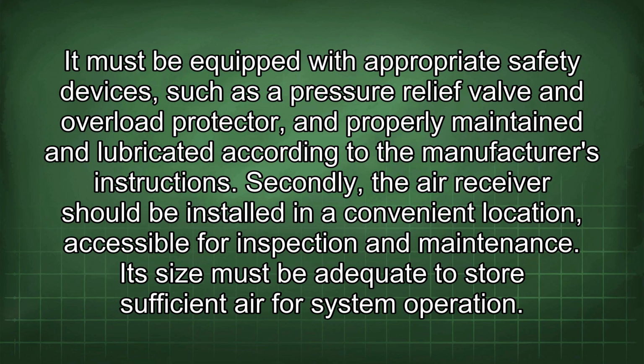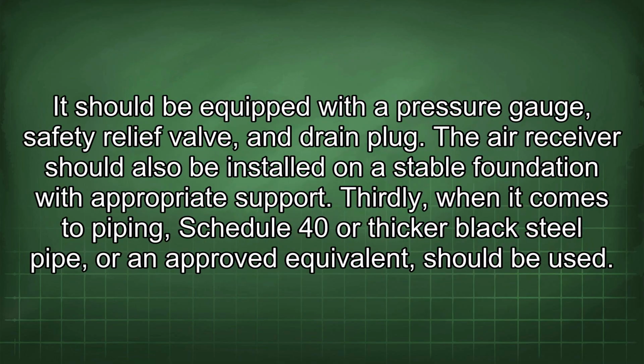Secondly, the air receiver should be installed in a convenient location, accessible for inspection and maintenance. Its size must be adequate to store sufficient air for system operation. It should be equipped with a pressure gauge, safety relief valve, and drain plug. The air receiver should also be installed on a stable foundation with appropriate support.